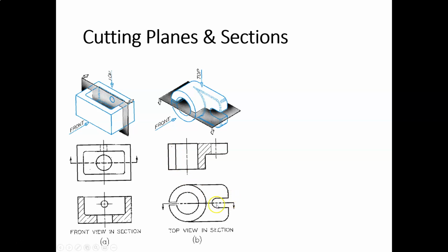Likewise here, this is a slot, an open slot. There's no material, and so there's no section lines here. The only place we're cutting through material is right here, and that's why there's section lines right here.